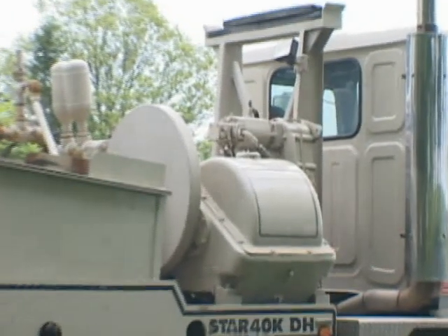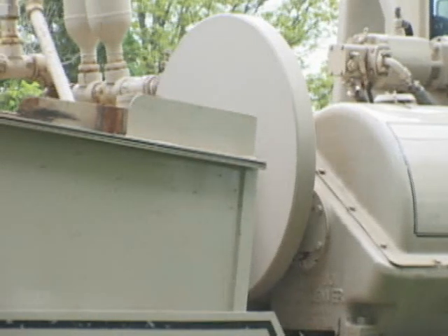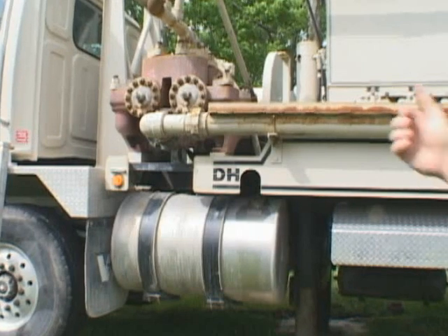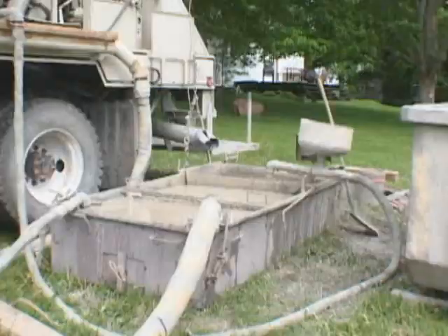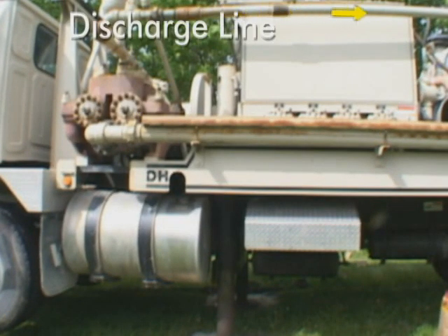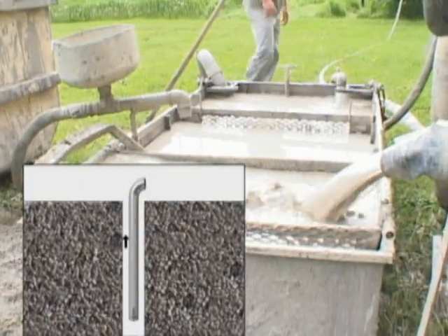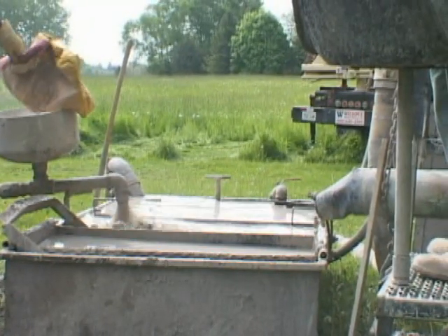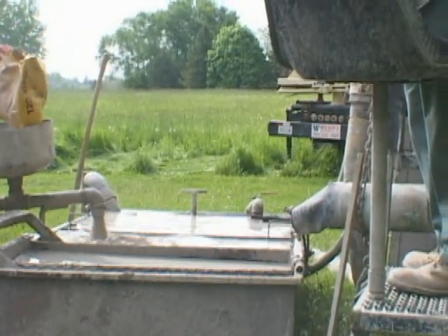The hydraulically powered drive end of the mud pump is shown, with the flywheel spinning. On the other side of the rig is the wet end of this double-acting piston pump. This is a closed circuit. The flushing media is pumped from the mud pit, through the suction line, through the pump, and discharged, either down the hole through the drill string, up the annular space back into the pit, or directly into the pit when mixing. The mud pit, through the use of baffles, helps to separate the cuttings from the bentonite mud mixture, as well as serving as a flushing media reservoir.